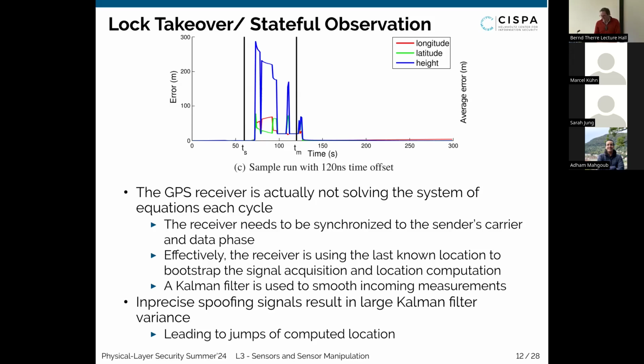in radio signals, you can simplify it and think about it again as just sine waves that are being sent around. The sine waves have a different time of arrival, a phase or something like this, and the receivers will always be tuned to these sine waves. They have to follow the cycle of the sine wave precisely. What is happening in this takeover is that the attacker will initially send signals that are exactly phase consistent with the real signals, and then later pull them away.